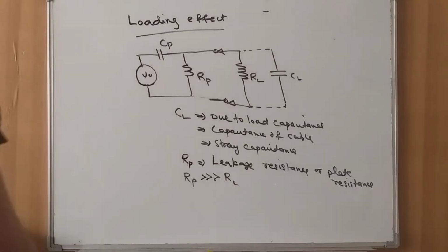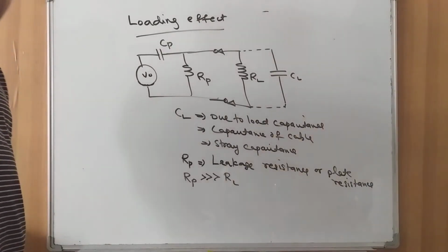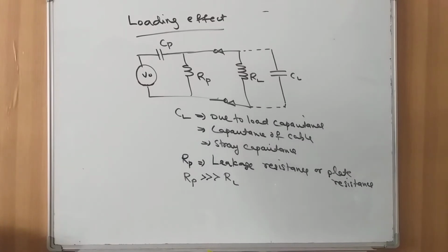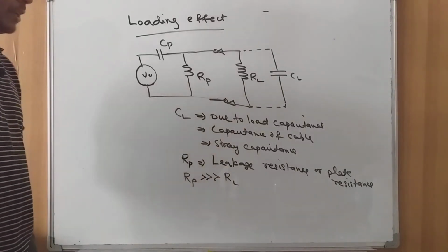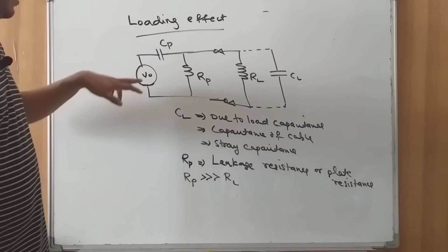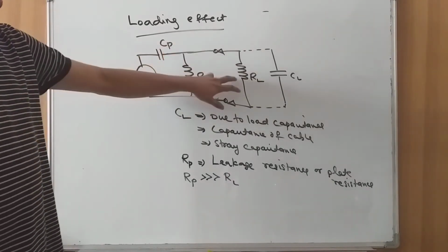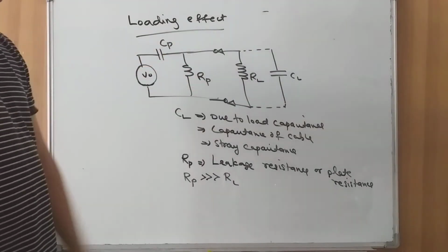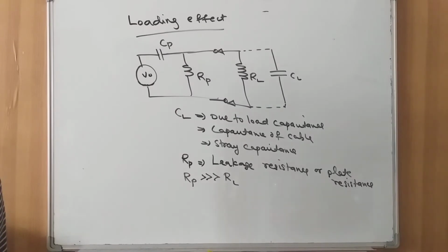Now, when we connect the piezoelectric sensor to an output circuit, definitely some effect of loading will occur. That can be calculated using the diagram here. This is the earlier circuit, and RL is the load resistor that is connected across the sensor.